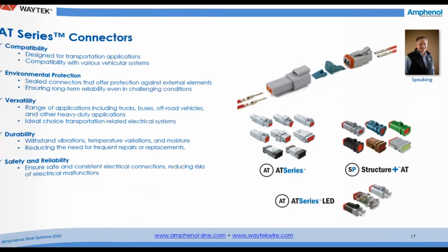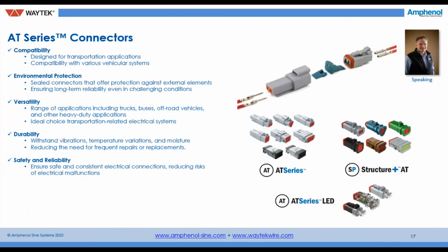Continuing on. We take a look specifically at our AT series of connectors, and in the top right picture, you can kind of see an illustration of that connector unassembled. You can see the wires coming in from the bottom left and top right to give you an idea of the contacts and how they're applied to the conductors, the housings, and then there's those wedge locks that we talked about earlier. That's going to secure those contacts into place and make sure that there's no movement. So for example, they can pass the rigors of that vibration test, and they're going to be durable over time.